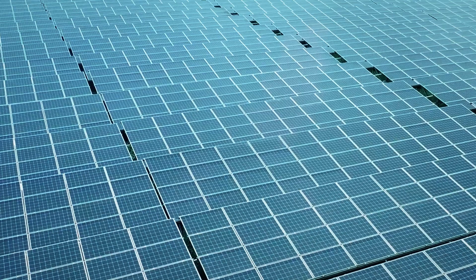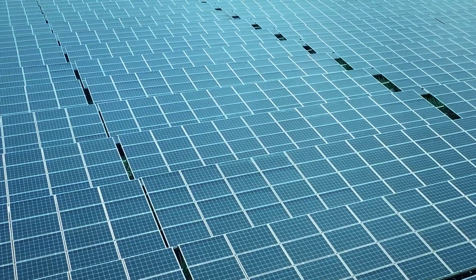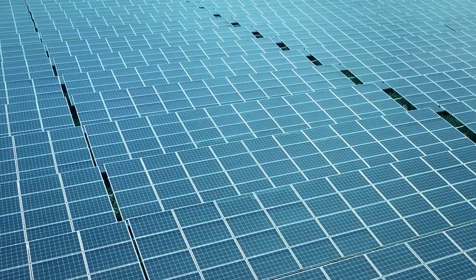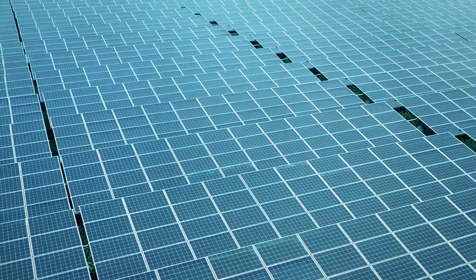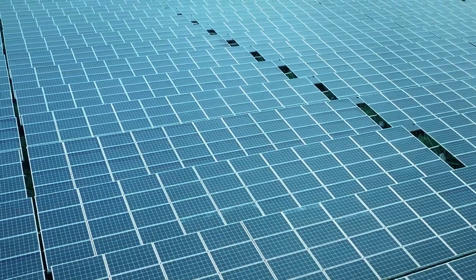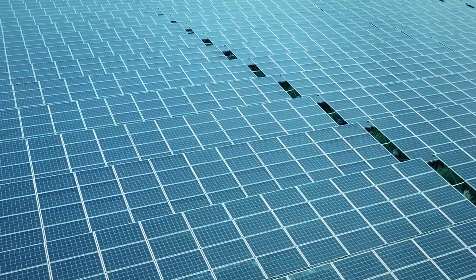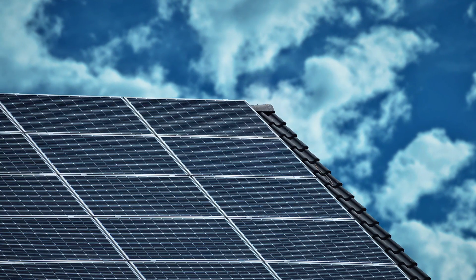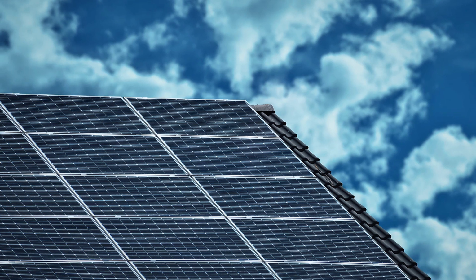Can you add more solar panels to an existing system? Yes. Creating a comprehensive tiny house energy system from the start helps ensure that you choose the components that best suit your needs. However, this isn't always possible. You may not have the funds to invest in all the necessary equipment upfront. It's also common for people to underestimate their electricity needs, so they choose to expand their system later. If you think you might want to add to the system over time, choose an oversized inverter to accommodate future energy capture.